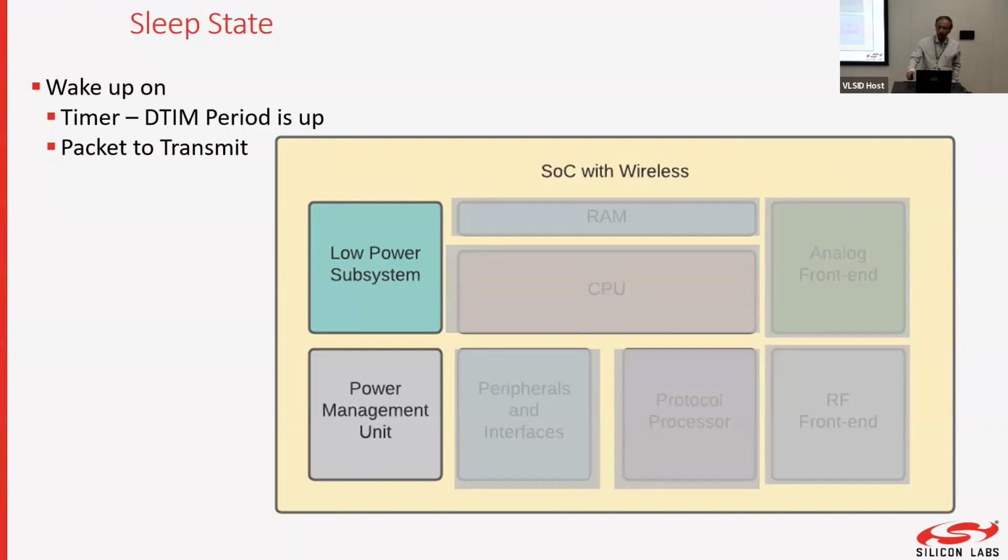Suppose I move this device. That means that I want to start using this remote control. So when I pick up the remote control, I want the SoC to wake up. So you need a sensor that will sense motion. And there are multiple ways of doing it. One is using a small ball sensor, a micro miniature circuit in which there's a small metallic ball which keeps moving. The more you move it, the more it shifts between 0 and 1. If you don't move, it stays at one end of the small tube.